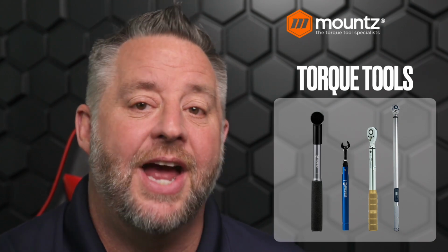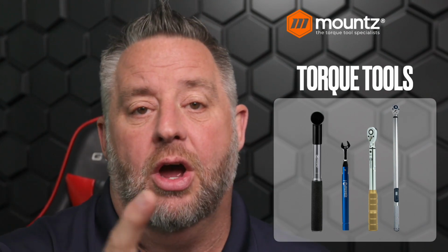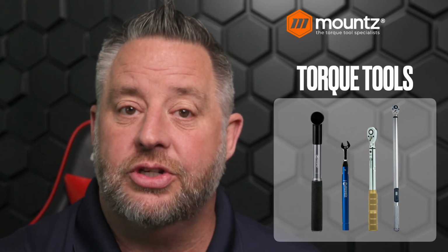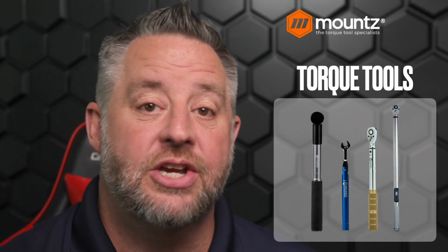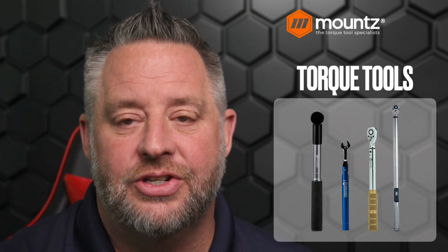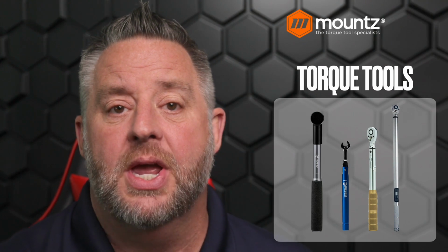But the next wrench is going to be a breakover style wrench. As this wrench is used, it breaks over, so the head will simply start to cam once torque is achieved with this style of wrench. Again, this gives you, the operator, a very solid indication that torque has been achieved. Then the next style of wrench is the click wrench. The click wrench is a very good and accurate wrench.